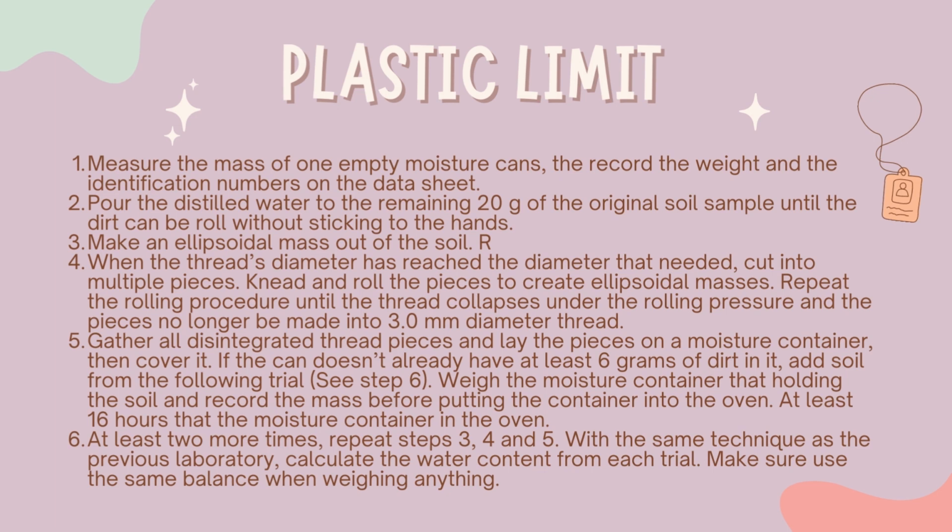Repeat the test at least 2 more times. Repeat steps 3, 4 and 5 with the same technique as the previous laboratory. Calculate the water content from each trial. Make sure you use the same balance when weighing anything.